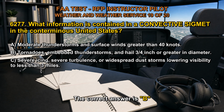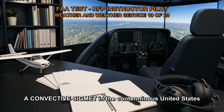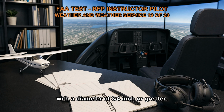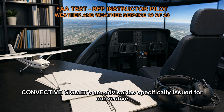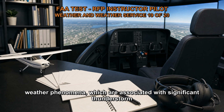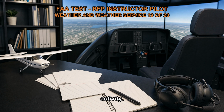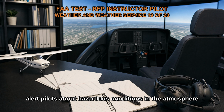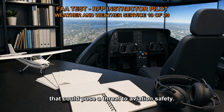The correct answer is B. A convective SIGMET in the conterminous United States contains information about tornadoes, embedded thunderstorms, and hail with a diameter of 3/4 inch or greater. Convective SIGMETs are advisories specifically issued for convective weather phenomena, which are associated with significant thunderstorm activity. The purpose of a convective SIGMET is to alert pilots about hazardous conditions in the atmosphere that could pose a threat to aviation safety.